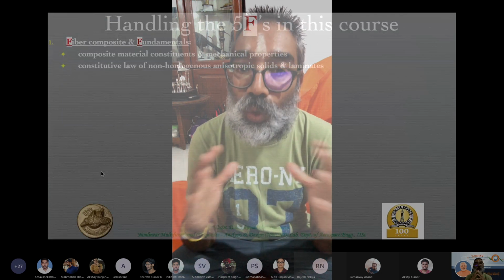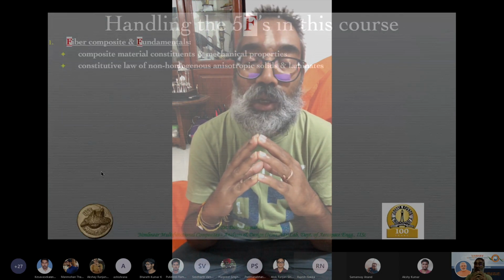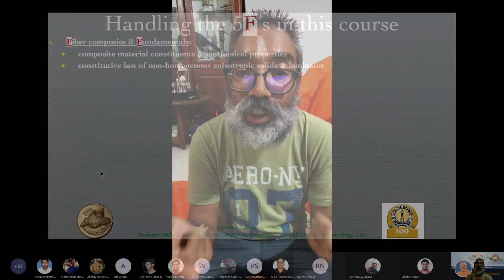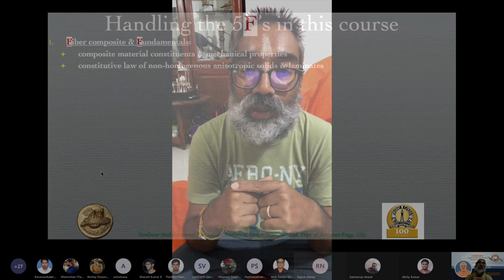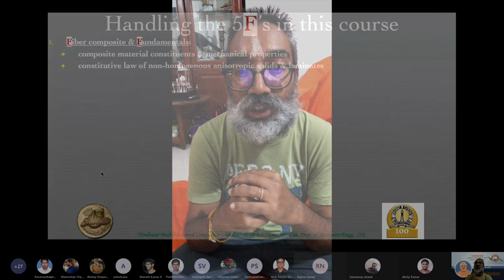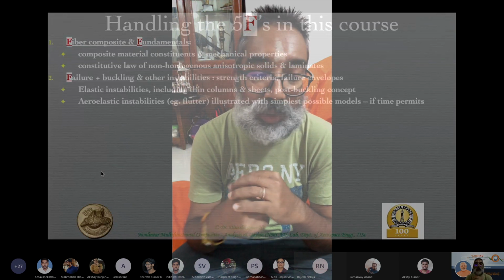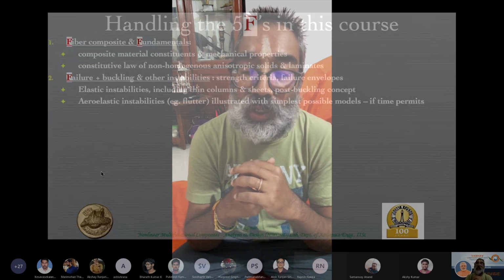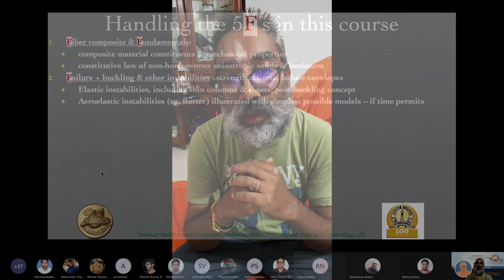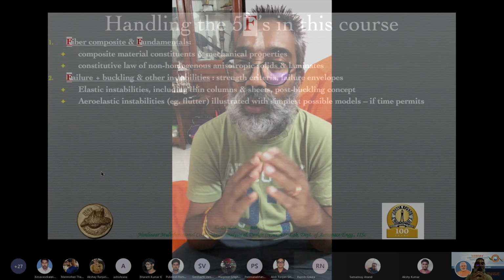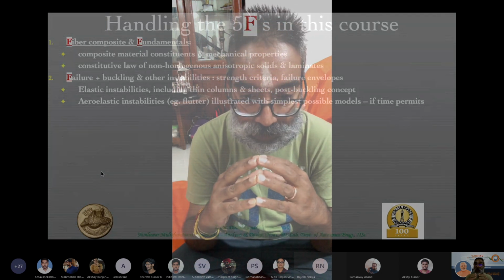And that serves a whole lot of purposes, both in analysis and design, even in detailed design. But you always have the opportunity to go back and understand what happens in the actual non-homogeneous structure later on if necessary, which is essential typically when you're trying to deal with damage mechanics. So that's what failure is all about, damage mechanics, in terms of the failure of the material. But then you have the failure of the geometry also, as we said, because of elastic instabilities like buckling and aeroelastic instabilities like flutter or divergence.